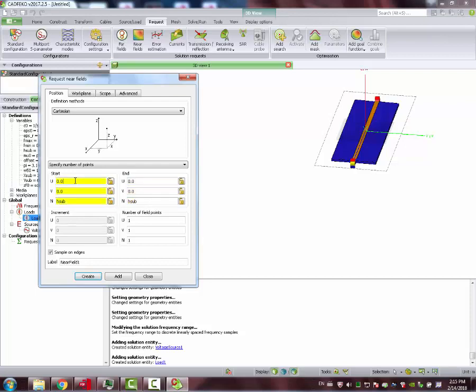And now we can get the starting point. We can type in any numbers that you need, but just Ctrl Shift. We select this point, and the second point, you see this is yellow here. I keep held Ctrl Shift. I click here. This is the first plane.